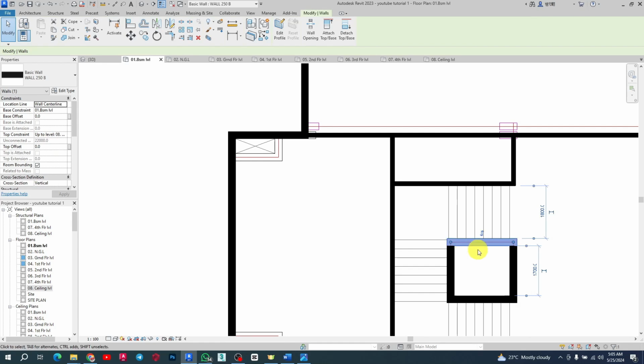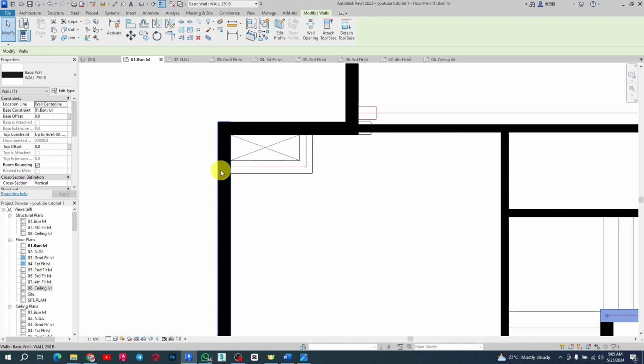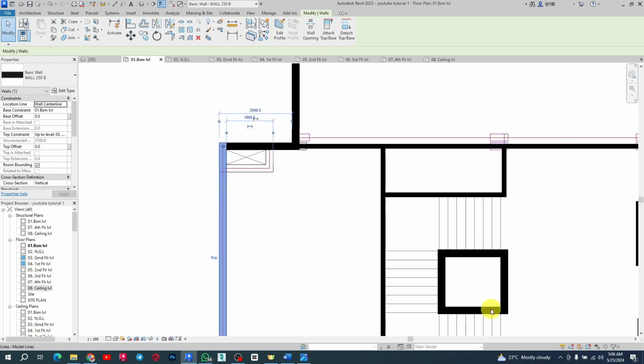So I'm going to click on a particular wall. When I click on this wall, I want to copy the property of this wall so that I can use it here. Since they all have the same property, I could still copy this property and use it here. But I want to copy just this one and use it at the ground floor, so that it takes me right up to the ground floor.